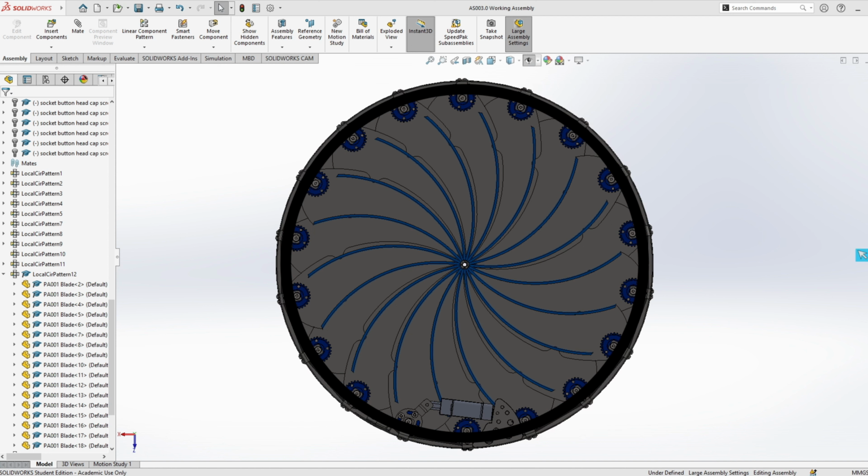So just to make it clear here, the large control ring usually surrounds the perimeter where the control ring moves freely in both anti-clockwise and clockwise directions. Several control arms, depending on the number of blades within the diaphragm, are connected to this ring, and the blades at the focused pivoting points. So we'll set pivoting points.